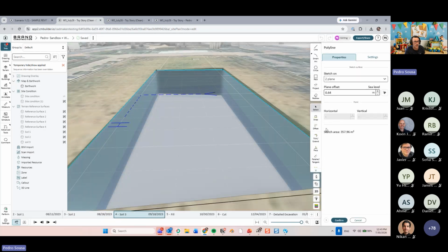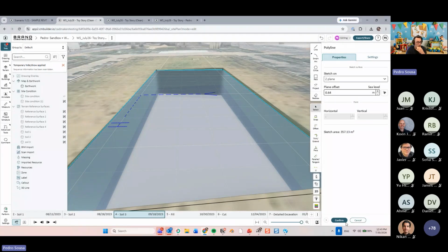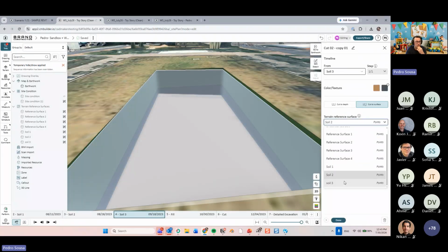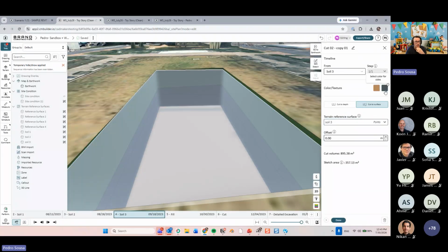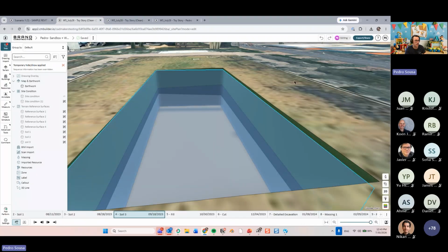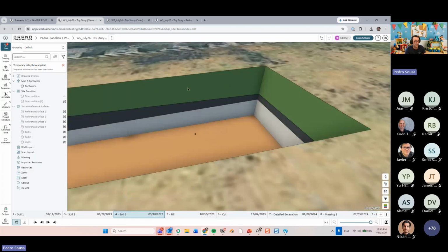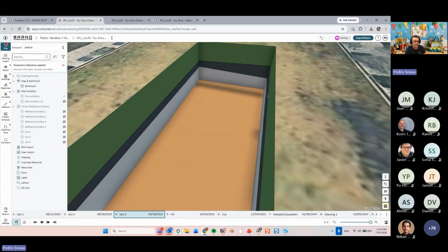And I'm gonna edit the sketch, do also like a minor offset over here so they are not sharing the same wall. Change this to soil 3, different colors. Bada bing, bada boom. I got my representation of soil profiles over there following my boreholes.